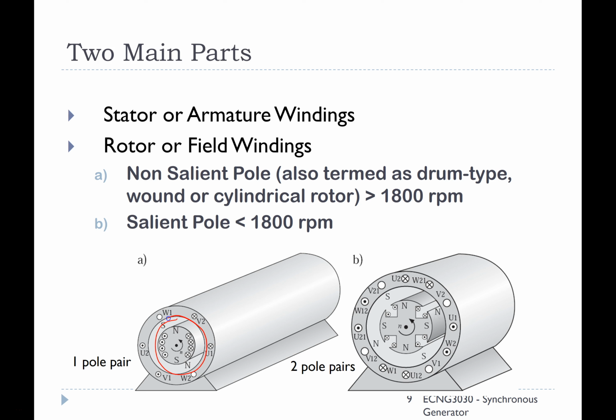The rotor, now there are two main configurations. We have what we call a cylindrical rotor, where you basically have a cylinder of soft iron and you place the conductors within it. And then the other one is what we call a salient pole. Salient simply means sticking out, and you could get here more than 2 poles, and you'll see north south alternating, just like we did with the induction machine. And this has its independent excitation.